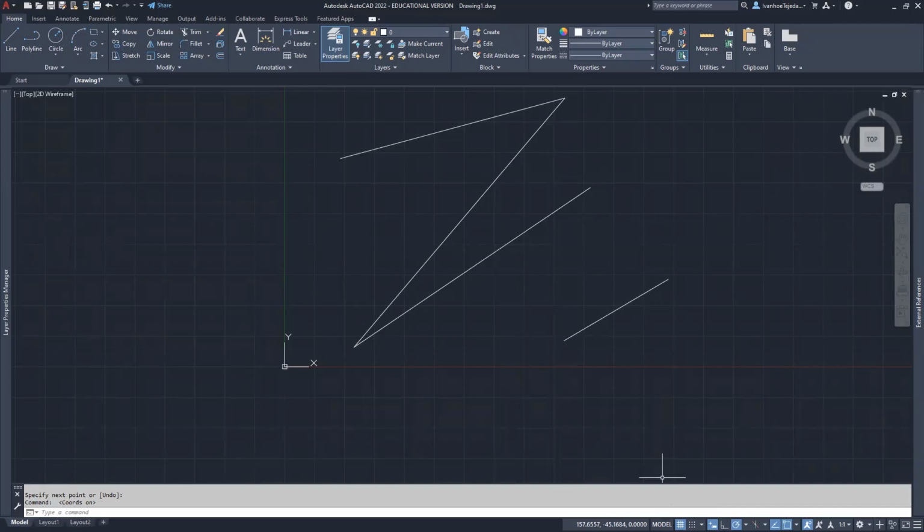And then after that, I have my drawing aids. So this one here displays the drawing grid, and it's active right now. That's why you see it in blue. But if I click on it, that means I am toggling it off. So one click makes that grid go away. And you're going to see me turn that grid off a lot. The reason for that is because I've grown up with AutoCAD and I'm used to not seeing a grid. They introduced this grid a few versions ago. For me, it's distracting. But I know that for students that are starting to use it now, they get used to it, they're comfortable. So it's a matter of personal preference, and I'm okay with that.